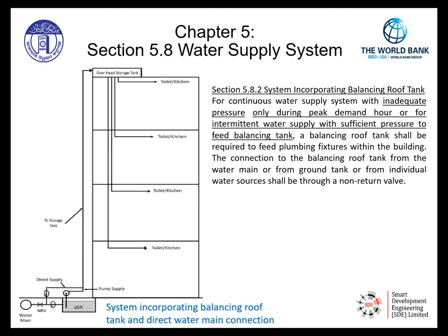The connection to the balancing roof tank from the water main or from ground tank or from individual water sources shall be through a non-return valve.